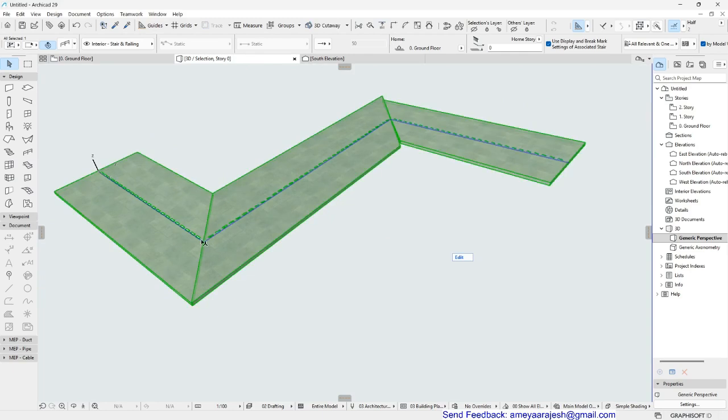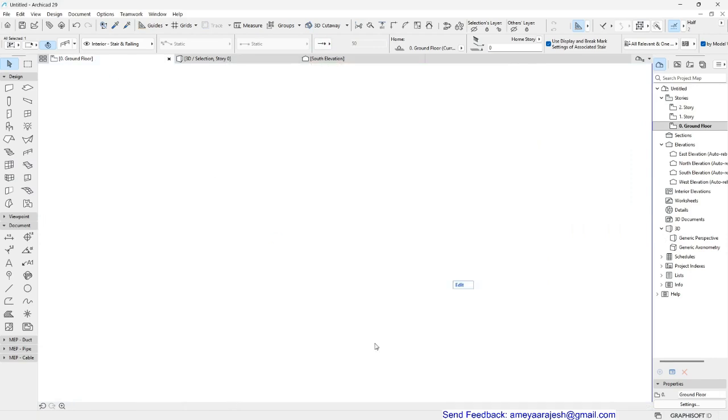Again, remember while drafting, what are the settings I have kept as center justified. Reference line position was center justified, not offsetted, but that depends on your comfort. Center justified was much better and convenient for me, so I have done that. Anyway, back to the floor plan.